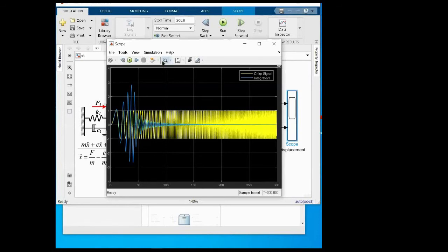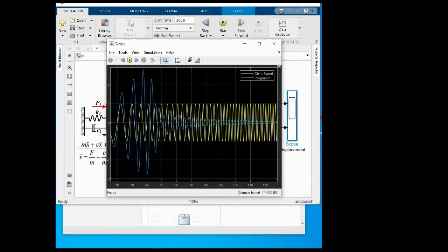We will use a zoom to show the results. The yellow color is our excitation signal, just a sine with different frequency in time. And blue color is the solution of our system. We can see that there is a resonance. We just pass through the resonance, and then we go further, and the system at higher frequency has no reply at all. It just will have zero at very high frequencies. Okay, this is a variant of working with the simple first order vibration system.